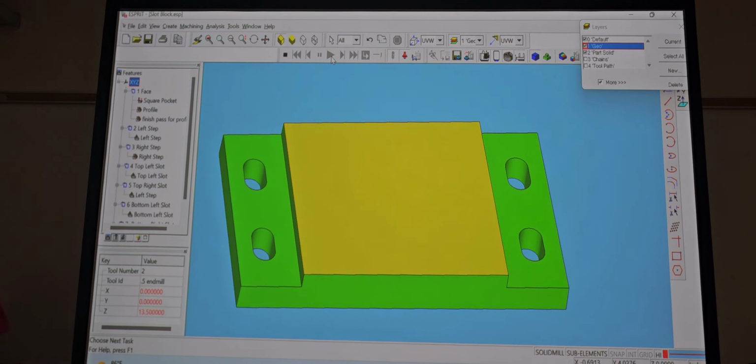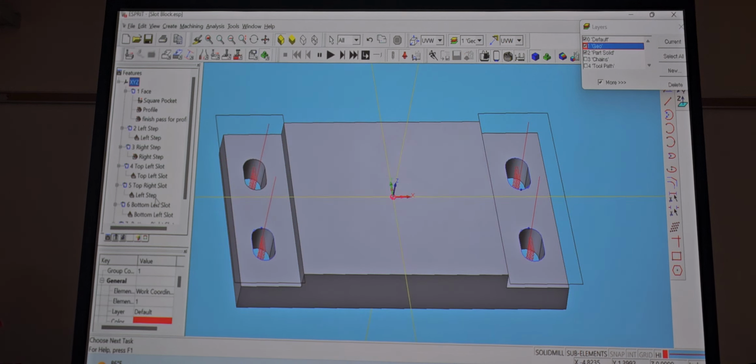That's one thing I always forget, is when I create new things, I always have to go and change the layers. And just as long as you do that by the end of it, you're fine, because you can always go back and do it, right? So I'm pretty sure I have some layers that are messed up right now too. If I click on that one, it's still in the geo, right? It's supposed to be a chain, but big deal. I just changed it to chains, and that's it, right? This is a toolpath, it's in the geo. Big deal, go to toolpath.